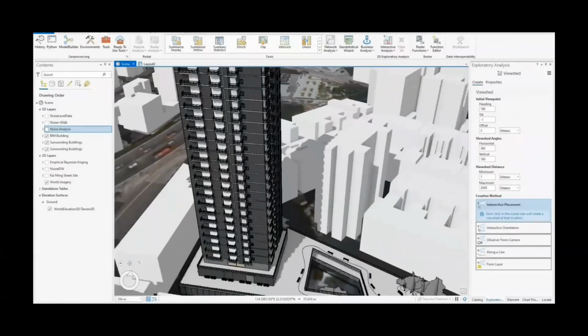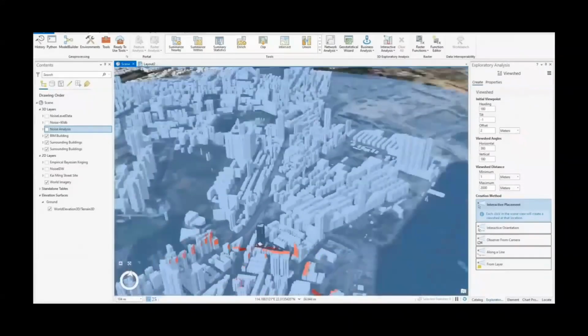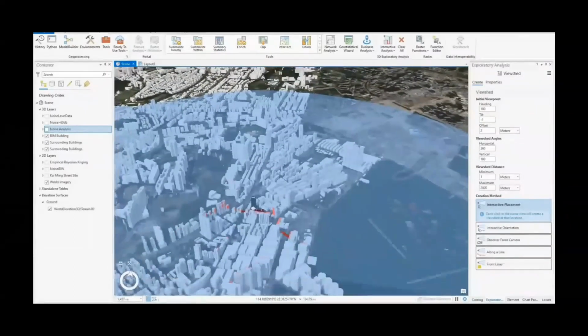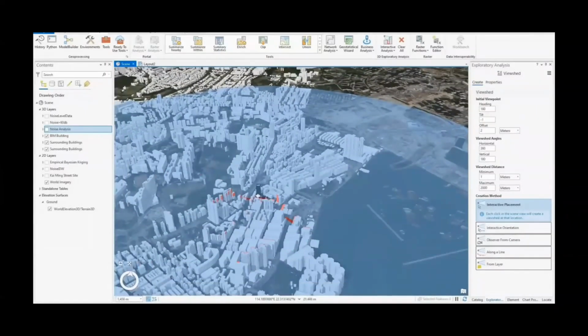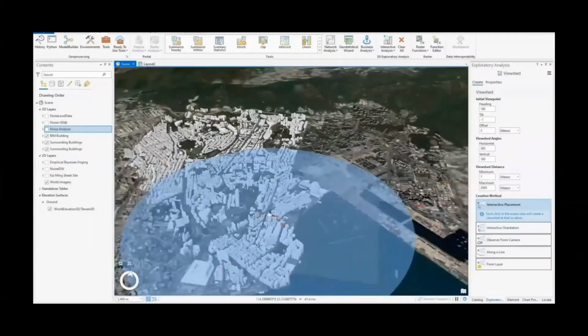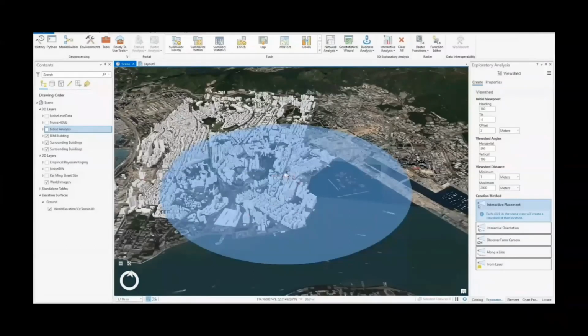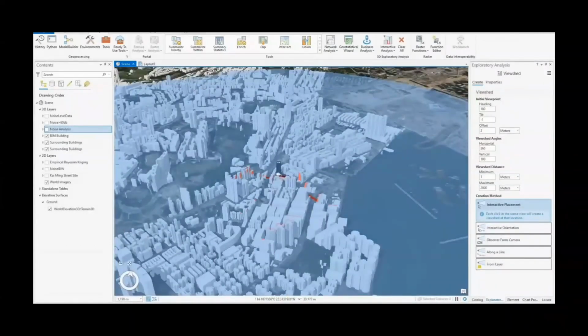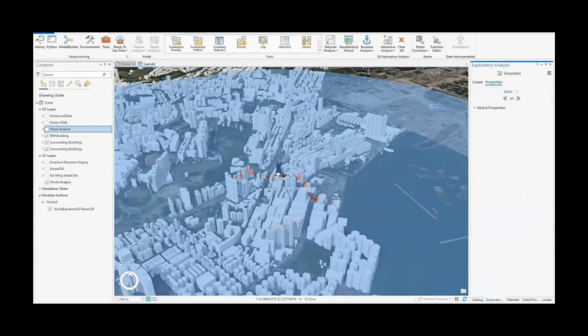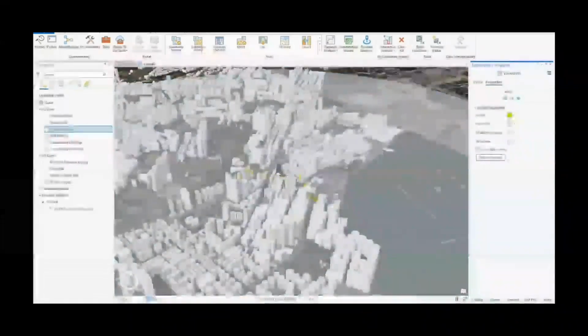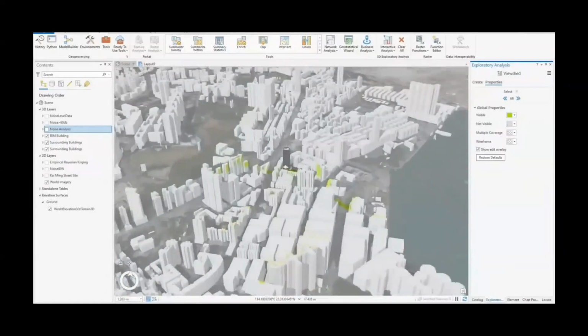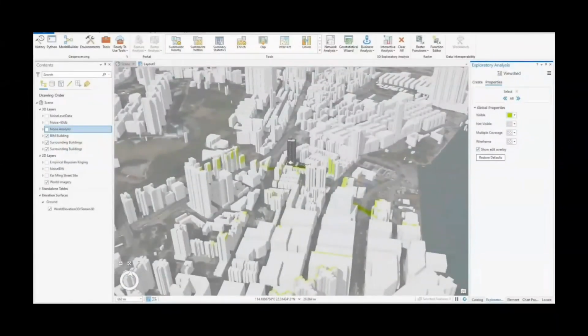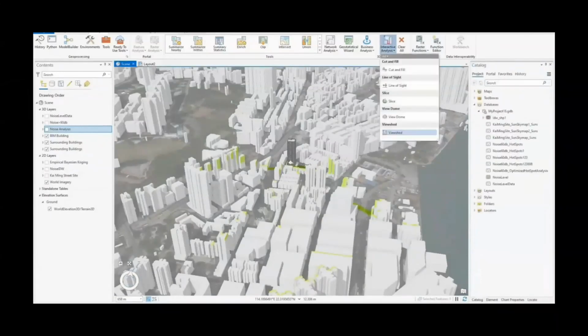So what if we put the vantage point at the bottom-most flat of the south-facing side? As you may see, most of the sea view is blocked by the Hong Kong buildings, and the red area is very limited due to the blockage by the surrounding tall buildings. So this is the power of the interactive analysis: it helps us simulate which flats enjoy more sea view or more enjoyable views for the residents, without the flats being physically constructed or physically visited. We can also change the color scheme of the visible and non-visible areas through the properties menu.